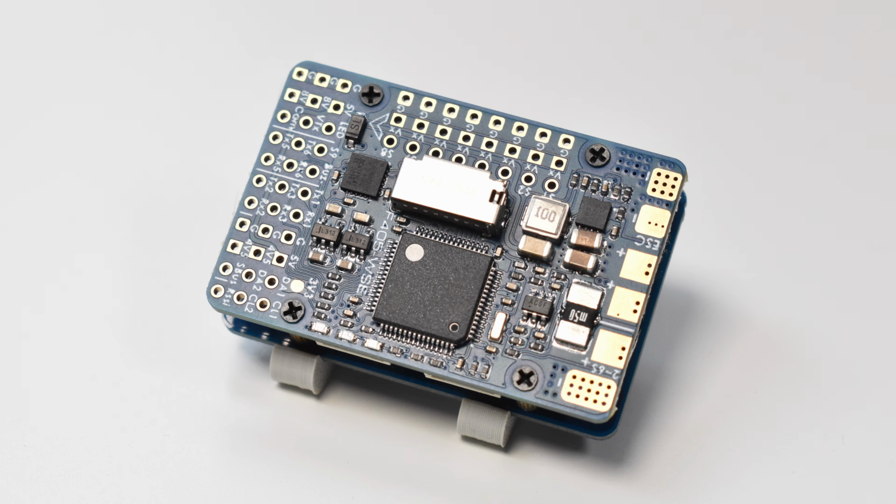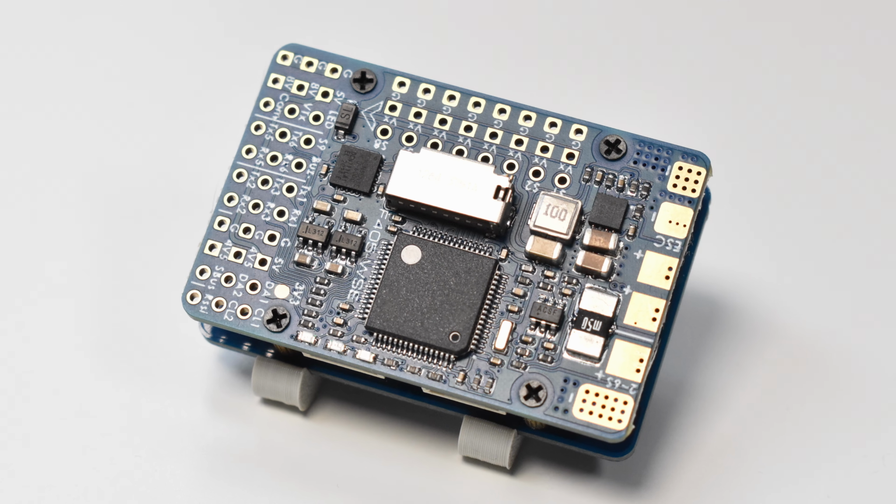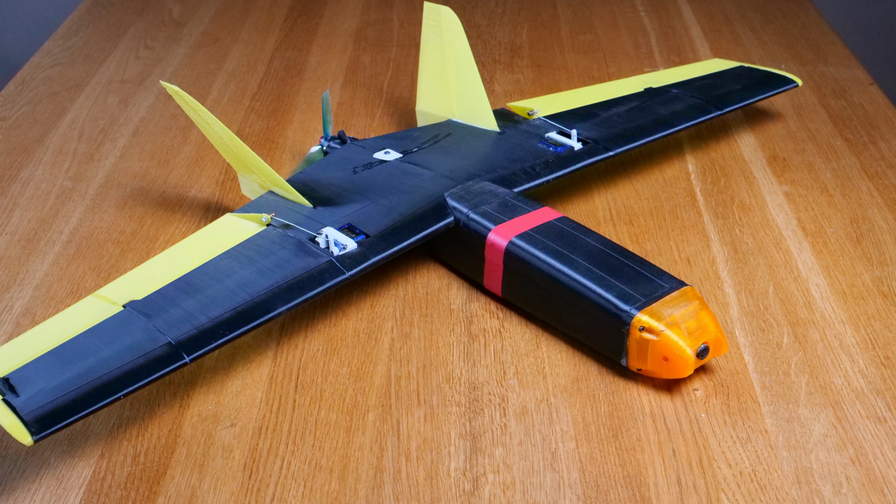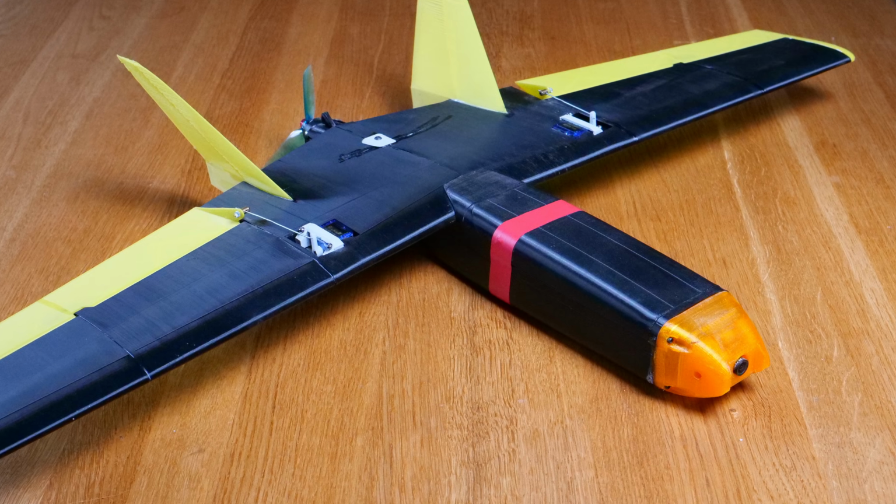Airplane-specific flight controllers just have beefy voltage stabilization, 3, maybe even more amps on the 5 volts only to power the servos. And of course, because there are no strict form factor limitations in airplanes, they can have totally different shapes and sizes. Sky is the limit. As we are on the topic of the flight controller form factor, there is no standard form factor for airplane flight controllers. So when getting one for your first or next airplane, the only thing you really have to check is: will it fit inside your model?